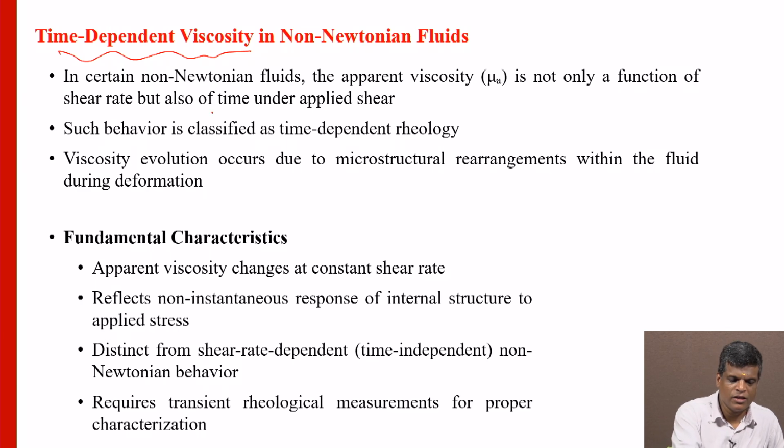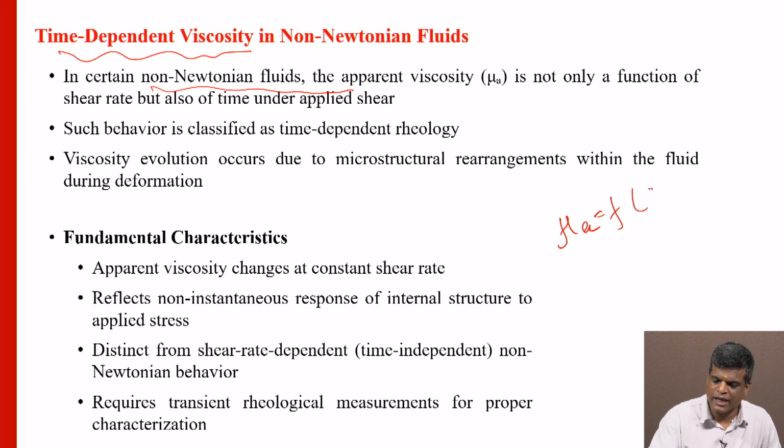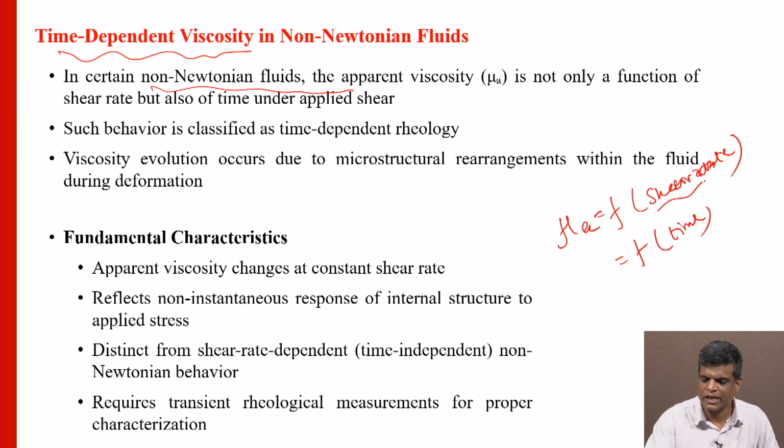But in this case, in certain non-Newtonian fluids, the apparent viscosity, we always discuss mu A, the apparent viscosity, is not only a function of shear rate, but again a function of time also. That's the only thing we are adding here. It's not only a function of shear rate, it's a function of time also. It's a time dependent viscosity.